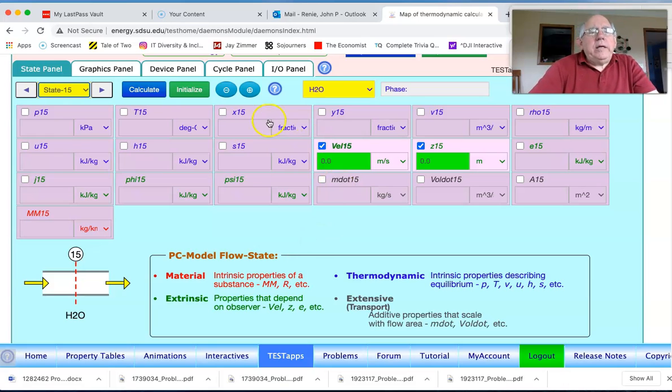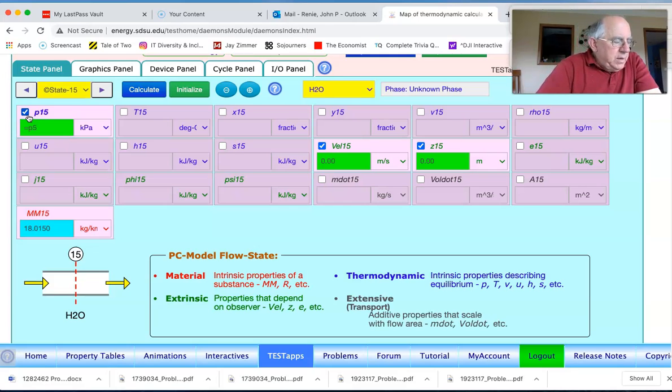And so what we know about that is the pressure there is the same as pressure 5. Okay, it's expanding to the same pressure. It no longer is isentropic. We do know that the m dot is equal to the same m dot 5. Okay, and that ended up being 15 kilograms per second is what we're taking out there.